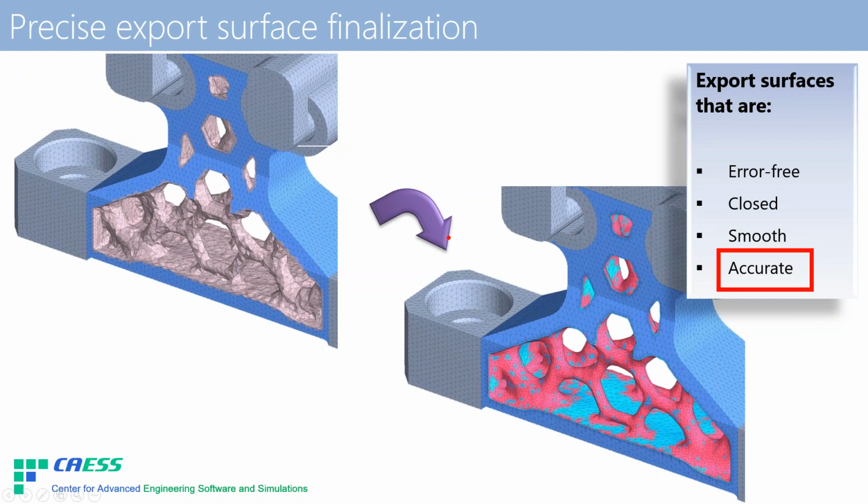which is very important, this smoothing has to be done accurately, because if the changes of the geometry are too large, and this happens very quickly, the engineers are typically very sloppy about this. If the geometry changes too much, even if it looks nice with curvature, the stresses can increase very quickly to a significant extent. So one really should be careful about this. Okay.